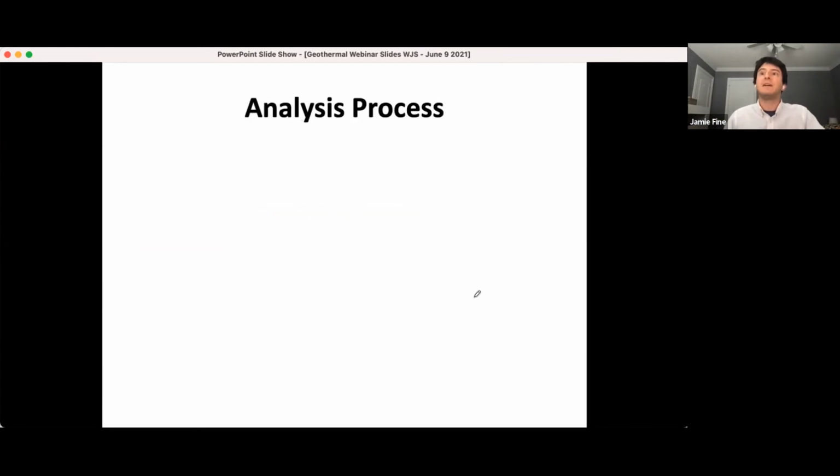Okay, so how was the analysis approached for this building? Well, number one, reviewing the system drawings. Coming up with that schematic on the previous page wasn't something you could do by just looking at the outside of the building and deciding, oh, that's how we're going to install a ground source heat pump. What I went through was looking at the detailed mechanical layout in detail, looking at the building automation system data and saying, okay, this is where the ground source heat pump could fit in.